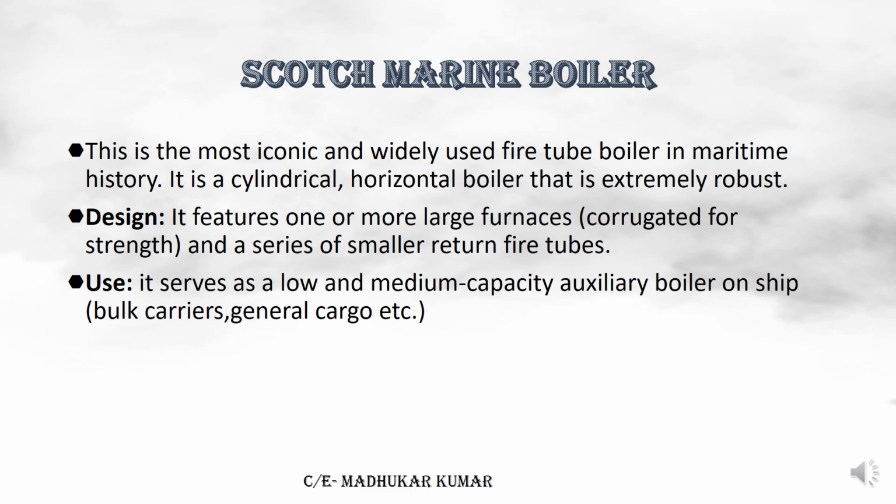Now the Scotch boiler. It is also largely used for marine purposes. It is a fire tube boiler, a cylindrical horizontal boiler, extremely robust in construction. Design features: it has one or more large furnaces, corrugated in structure to give structural strength, and a series of small return fire tubes. So this is the Scotch marine boiler. A low and medium capacity auxiliary boiler on ship, utilized basically on bulk carriers, general cargo vessels and all.